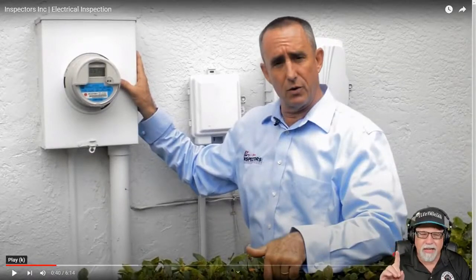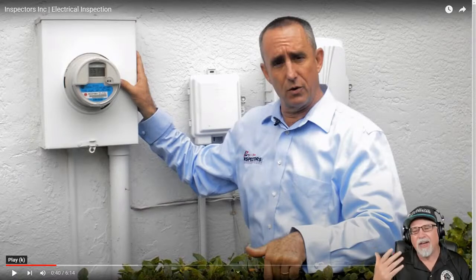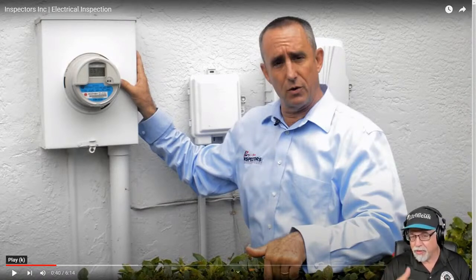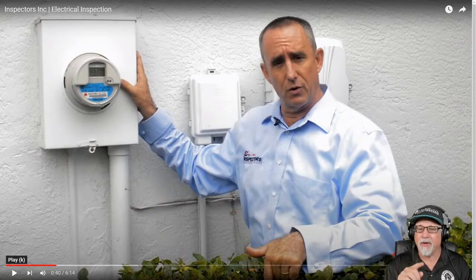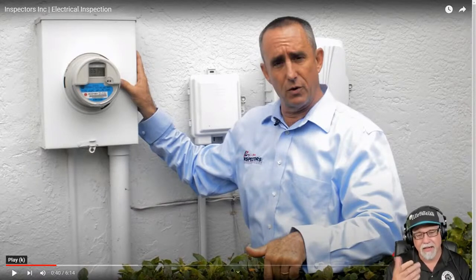You know, one thing I noticed real quick is that meter does not have a tag in it. So somebody could just come up, flip that up, pull the meter out. Now, I know if there's a little tag in there, somebody could also come and cut it. But in this case, there is no tag. So if I'm doing an inspection on the existing dwelling, by the way, I'm going to wonder if somebody hadn't done an upgrade or a service or something without calling the utility. Typically, they're going to have a tag in there, and it seals it. That way you know if anybody's tampered with it or not. I'm just saying, I just noticed that there's not one in there.